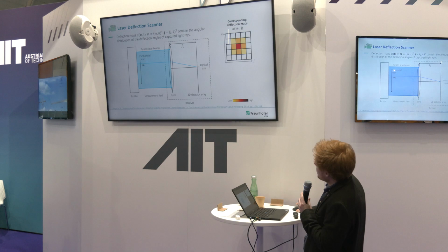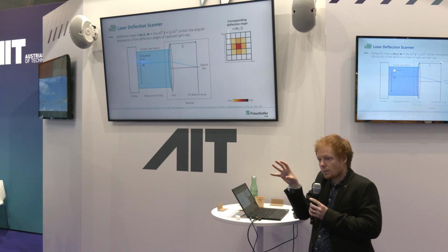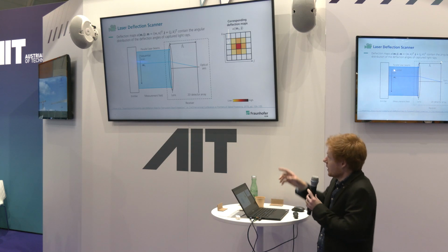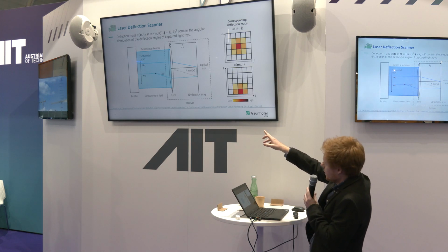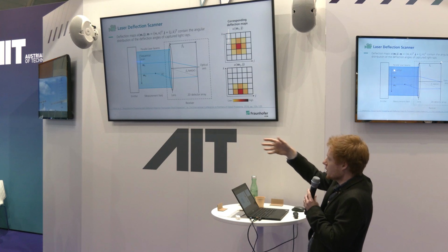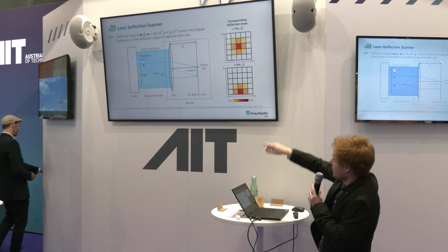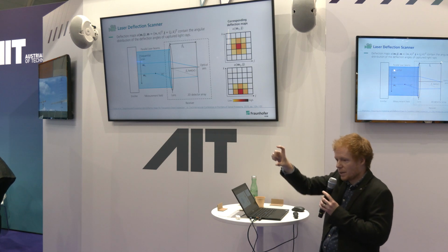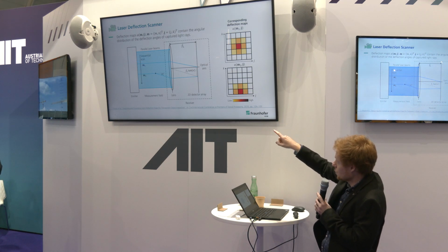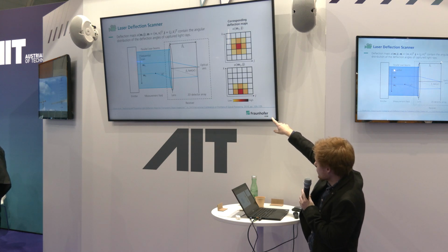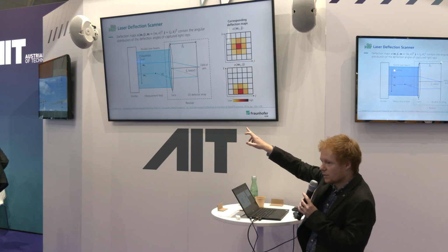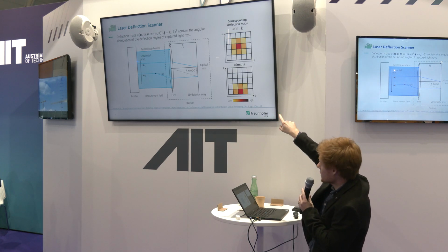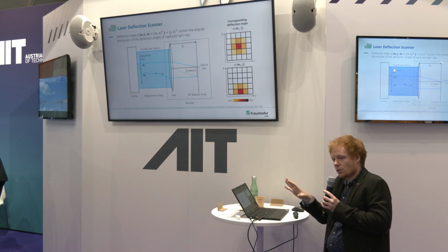And what we would sense here, we call those structures deflection maps. You can see them at the top here, the two-dimensional distribution of deflection angles that we get for this one measurement position. Now, for example, if at the position M2 in the measurement field, our ray gets deflected by an angle alpha, it will hit the detector with a spatial displacement that corresponds to this deflection angle alpha, and our deflection map would look something like this. So no matter where in the measurement field we have a deflection by this angle alpha, we would always get such an intensity distribution on our sensor.